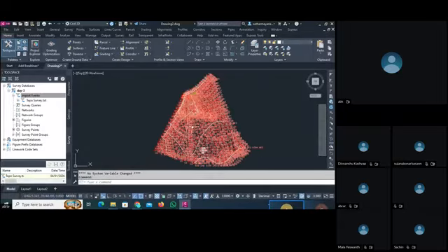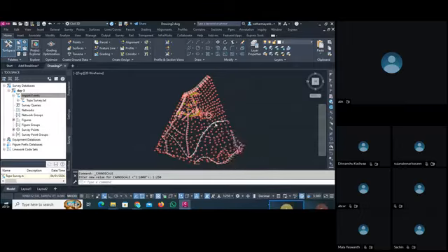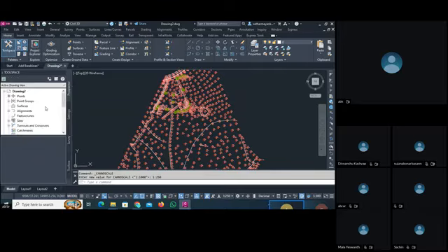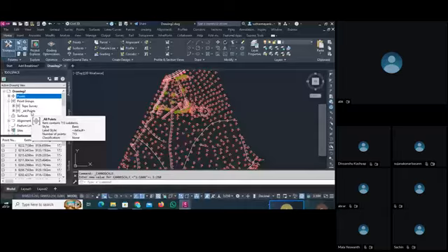As you finish it, you can see that we perfectly imported our data. I set my scale so I can see everything in a proper manner. We again go to the prospector tab, and let's check that our points are imported here. Now the second step, we go here to point groups. The topo survey we imported is shown here. And the second, all points: I already told you that whenever you import the points, Civil 3D automatically creates a point group. So it is not an issue.